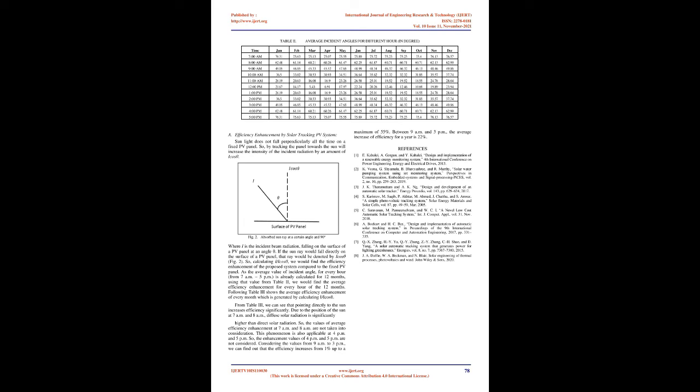Values obtained from Table 2 will be used in Arduino microcontroller programs so that it can move the motor at regular intervals. The following code shows part of the Arduino program. The values of the angle will be stored in myArray. The program will take data from this array and will move the motor. The function delay is used to maintain the position of the motor as well as defining the interval time between two successive movements. void position(float myArray, int days).